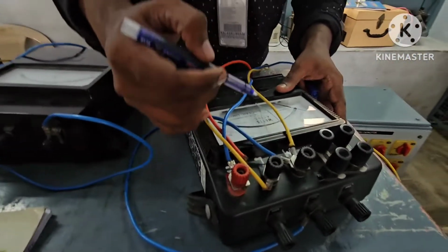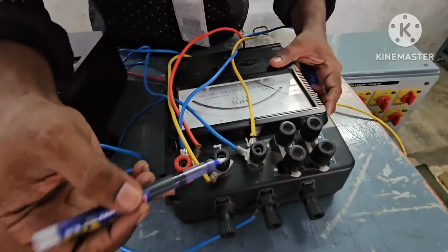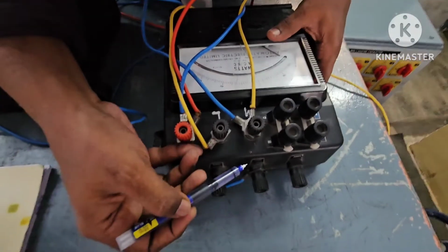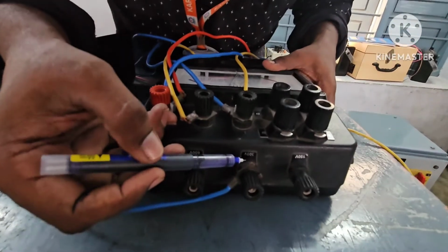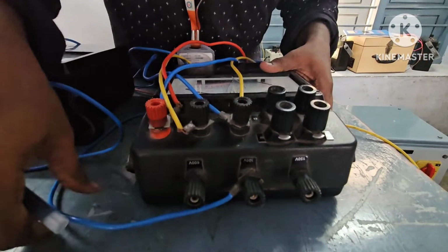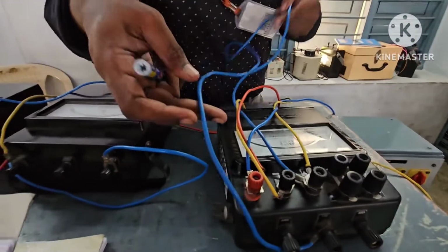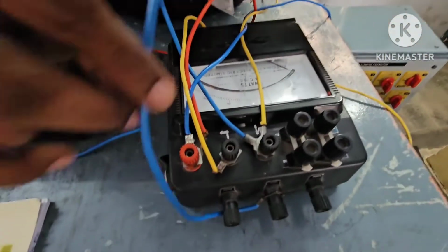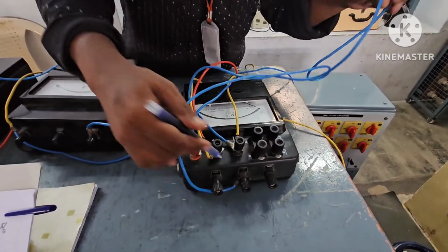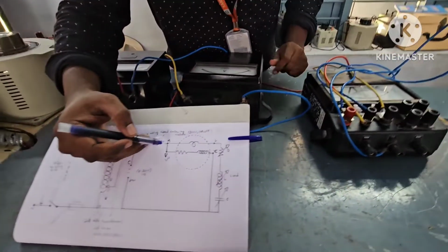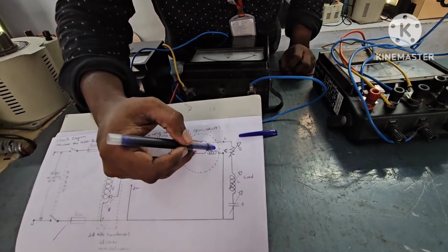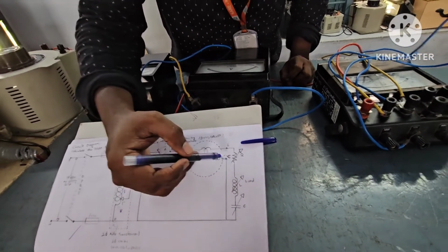So you see, I am going to use a wattmeter which is going to measure power consumed in a single phase load. So I choose the voltage range for this wattmeter as 300 volt. So I am picking 300 volt. The 300 volt I am connecting to wattmeter M. So M and V I am connecting using a wire. This blue color wire connects M and V, right? And then ML and VC are there internally, so there is no need of connecting these two.